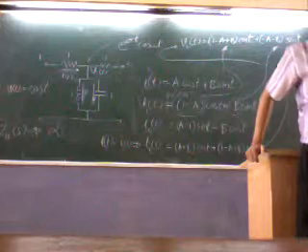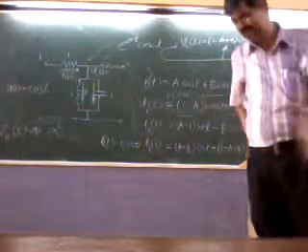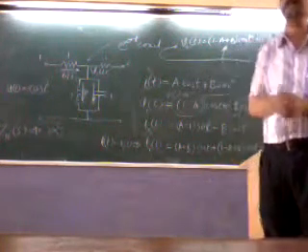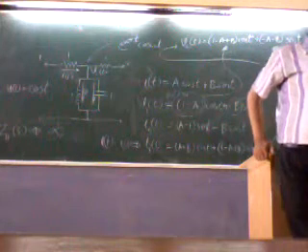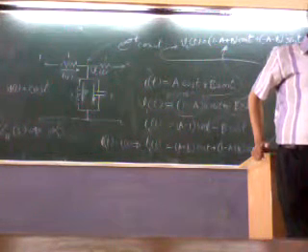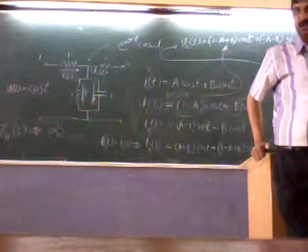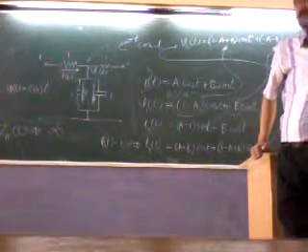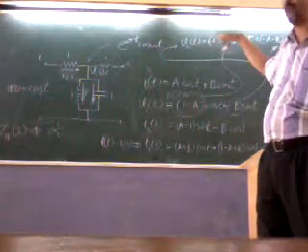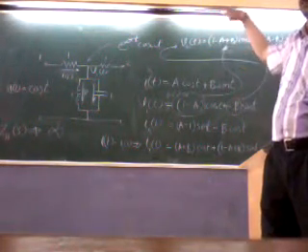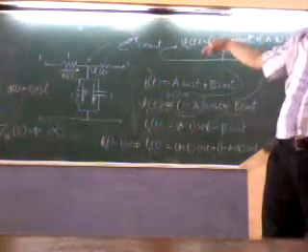What we may try to analyze in reverse way. Zero of impedance function is pole of admittance function. If I write Y11S, it would be S square plus 1 upon S square plus S plus 1.